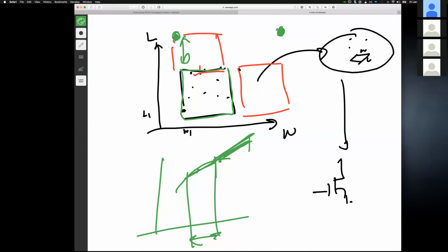But if you're extrapolating too much, in a way where the device wasn't characterized in that space at all, you're going to get a larger error, or you get a discontinuity where you put the model in a place where there's a discontinuity. And this is because it's not designed to handle this.